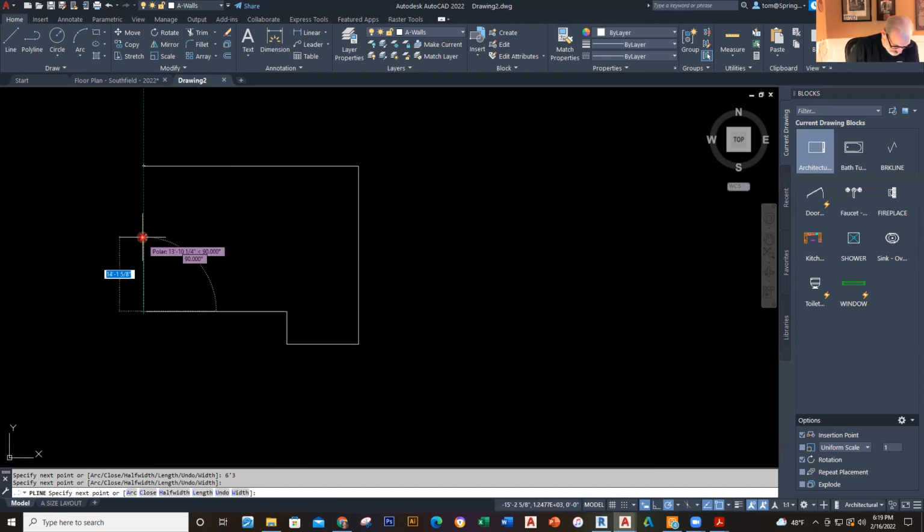Now, the distance I have to go here, I have to go down to the chimney. So the chimney distance, I've got to add that up in my head. So that's what, 6 feet, 14 feet, 11, 15 feet, 11, 16 and 5 inches. It looks like it is 16 feet 5. So I'm going to go down 16 feet 5. We'll see how close I am. And then I come back out this way. The actual projection out is 2 feet, and then the actual width of that is going to be 4'8".